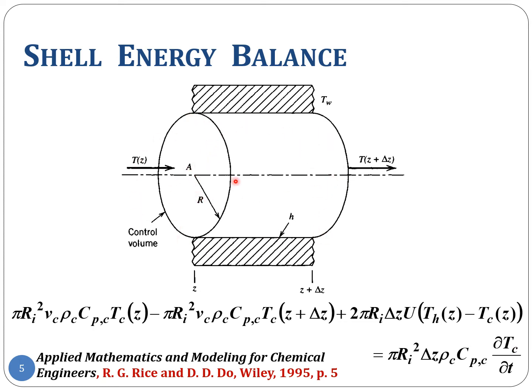This fluid is a flowing fluid, and therefore in this particular scenario, when the inner pipe fluid is flowing, the velocity or the momentum of the inner pipe fluid, which is the cold fluid in this case, is going to in turn influence the extent of heat being transferred, and therefore this heat transfer coefficient will turn out to be a function of velocity. Oftentimes in your heat transfer courses, you would have studied this as correlations between Nusselt number, which would be proportional to the heat transfer coefficient, and Reynolds number, which would be proportional to the velocity of the flowing fluid. Right.